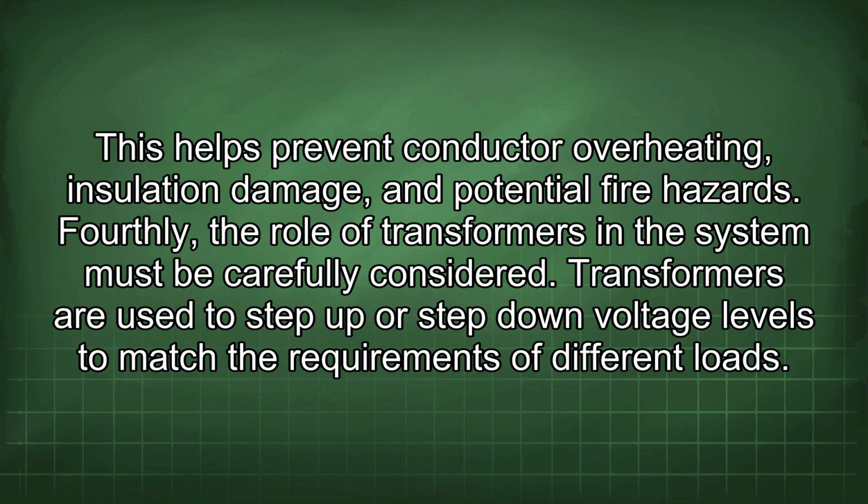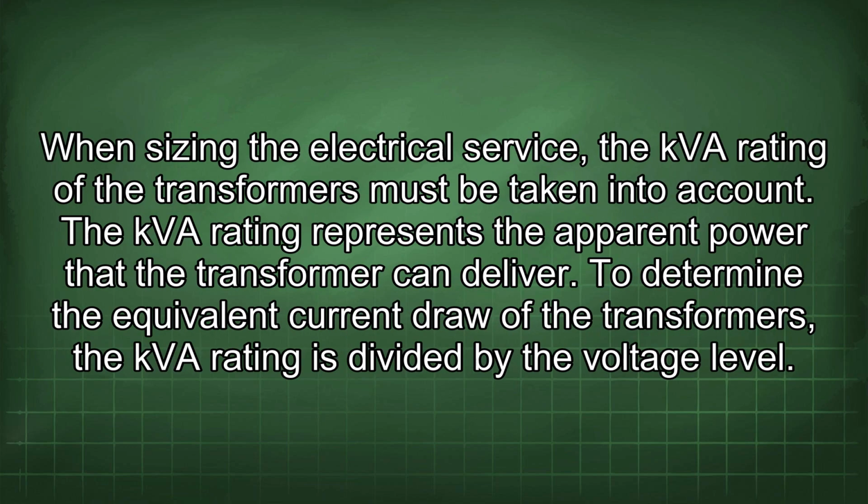Fourthly, the role of transformers in the system must be carefully considered. Transformers are used to step up or step down voltage levels to match the requirements of different loads. When sizing the electrical service, the kVA rating of the transformers must be taken into account. The kVA rating represents the apparent power that the transformer can deliver. To determine the equivalent current draw of the transformers, the kVA rating is divided by the voltage level.